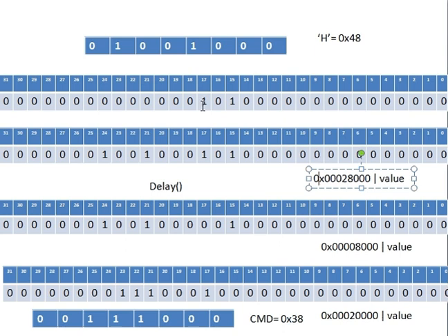Bit number 17 has to be 1 because this is enable. You have to enable first, then give a delay, then make it low. So now the enable pin is high, and the port 1 pin 15 bit is also high, which implies that you're sending data. If this was 0, then you're sending commands. This is how the controller comes to understand whether you're sending data or commands.